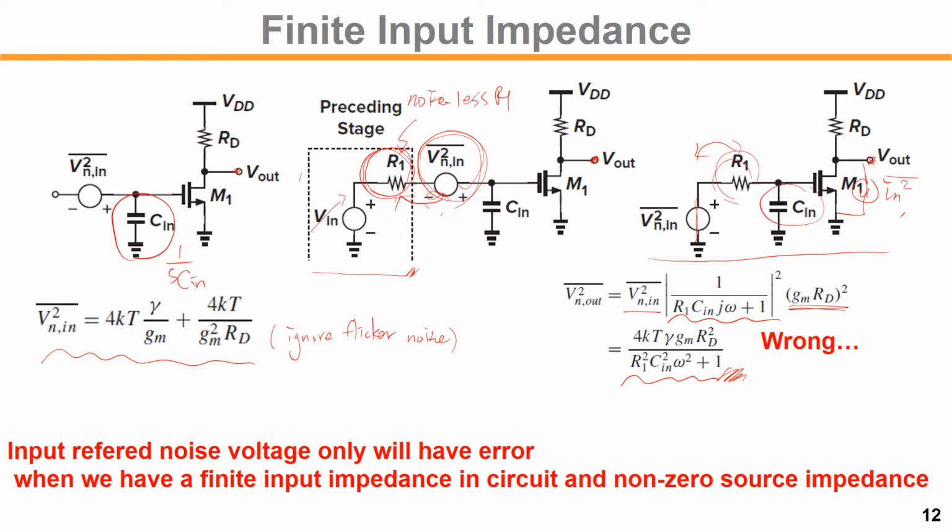If you assume that R1, the source impedance, doesn't have any noise, because we lumped all the M1 noise into the input referred noise voltage, then the output voltage should be exactly the same as this kind of circuit network: R1, all the noise from the transistor I_N1, and then noise from this resistor and transistor, right? That's M1 and I_N R squared M2.